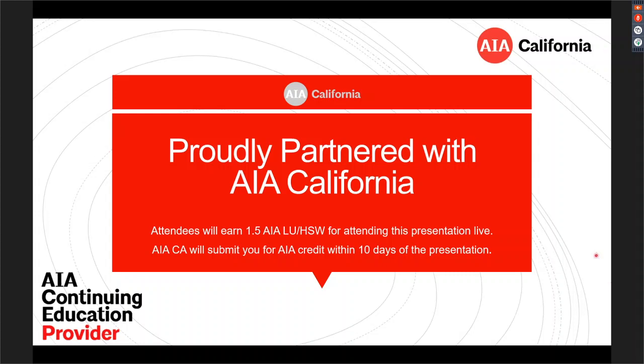Hey, Richard, this next question is regarding UL listings for head of wall conditions. The question reads, changes that do not materially alter the work, page 7 of your PowerPoint presentation, item 3 under notes refers to top of wall condition. Most approved drawings do not list the UL assemblies, so changing the top of wall system is a change or an NMA if it wasn't identified in the first place.